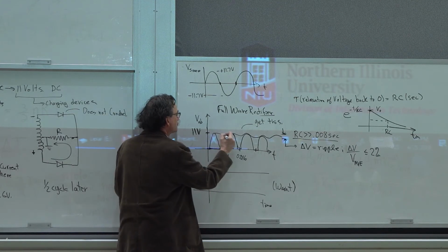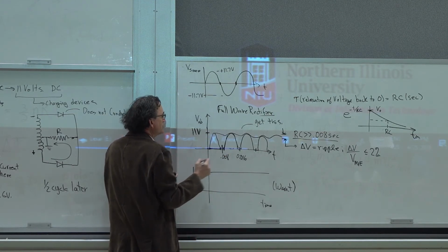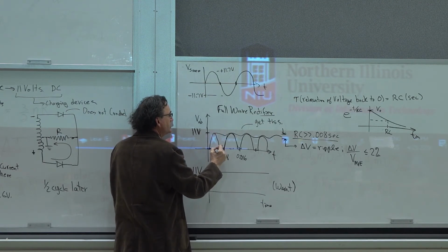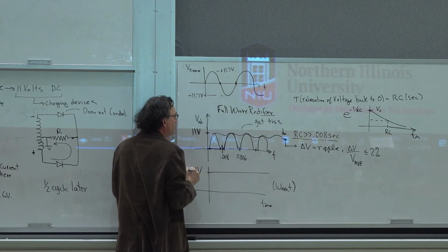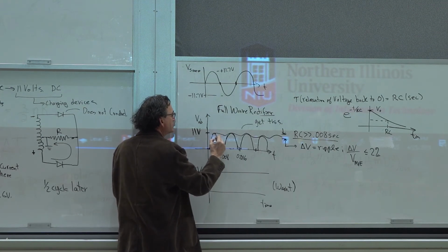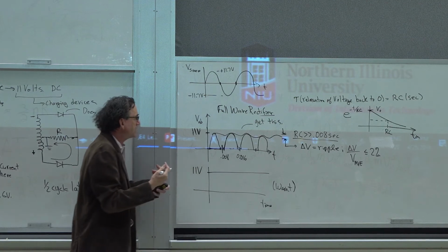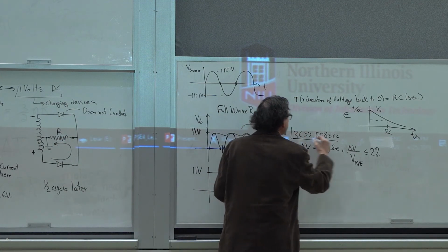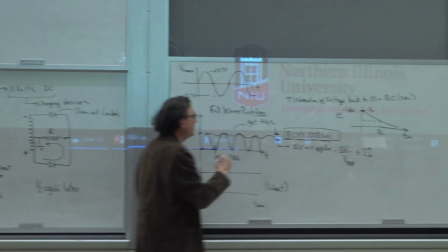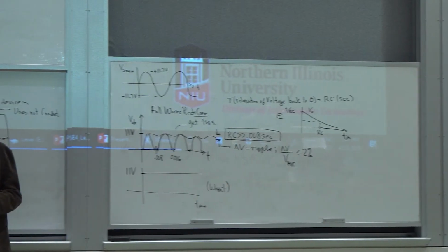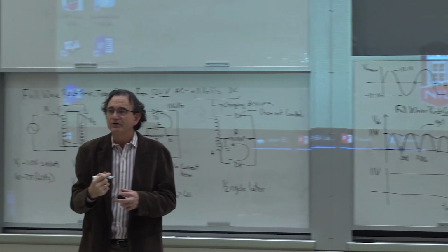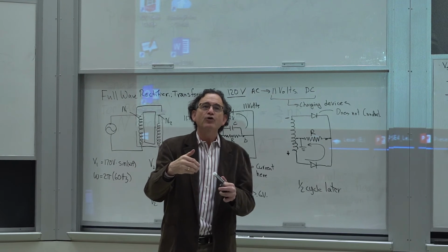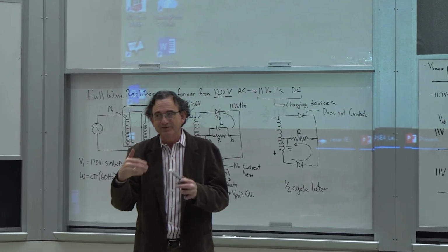you're trying to prevent this droop, right? The worst case scenario would be if I drop the voltage immediately to 0. It would still bleed with this time constant. But you're actually holding the voltage up. So I don't know a better way to describe it. As long as you satisfy this condition, then you can make that ripple less than 2%. You're just using the 2% as a parameter,